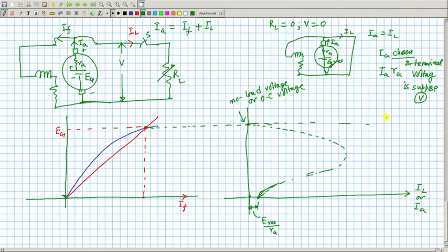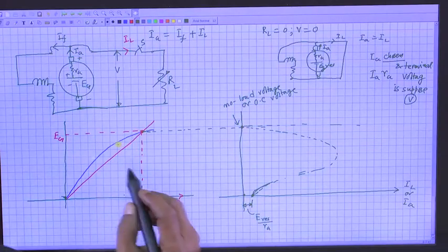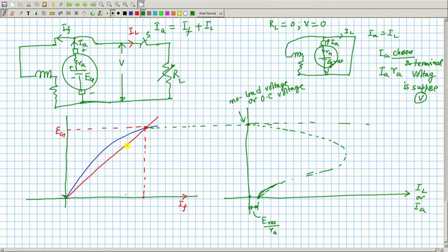If the terminal voltage is V, the voltage applied across the field circuit is also V, because they are in parallel. If you fix this voltage, then I will say, okay, the field current will be this much. That is, I will write here. So, I have chosen a terminal voltage. Suppose this is the terminal voltage. If this is the terminal voltage, this V, oh sorry, this part is also very interesting.